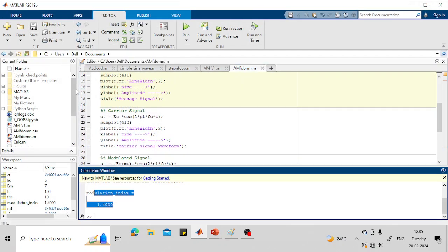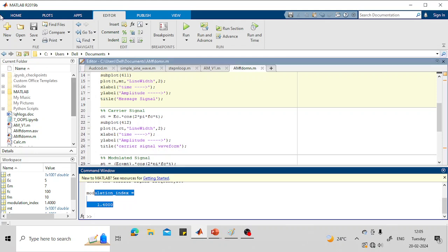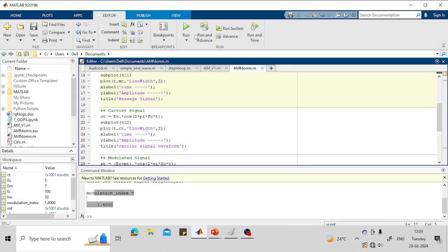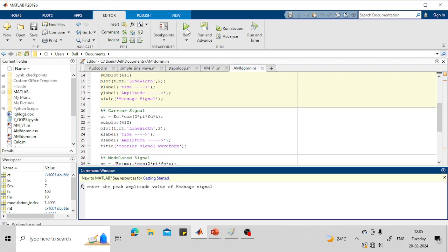Okay, so in the last set of simulation, running the program, I wish to go for changing the frequency also. Till now I kept the frequency constant. Now I wish to go for changing the frequency. Let us observe this. Amplitude, first iteration, whatever I took, like message amplitude 3, under modulation condition I am taking here message amplitude 3, and message frequency I wish to go for 20.